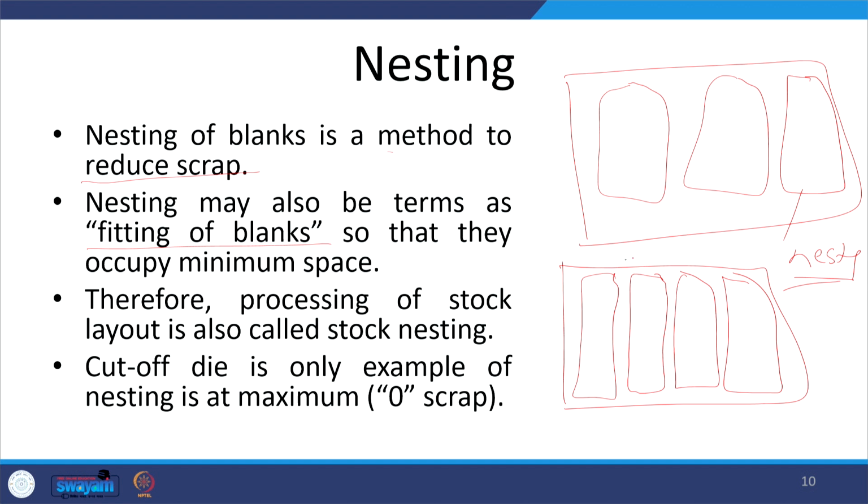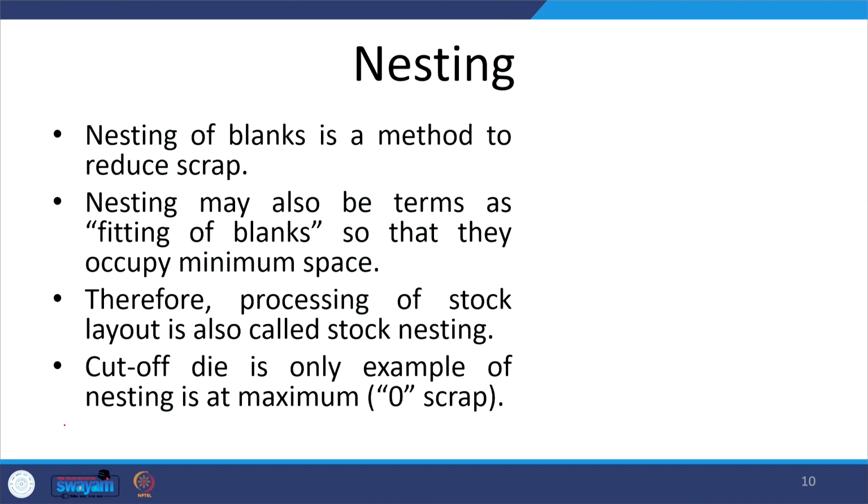Initially this will be made with the help of paper and pencil, to see how this fitting can be developed, what will be the orientation of the cutting, so that the maximum number of blanks can be produced. Therefore, processing of a stock layout is called stock nesting.